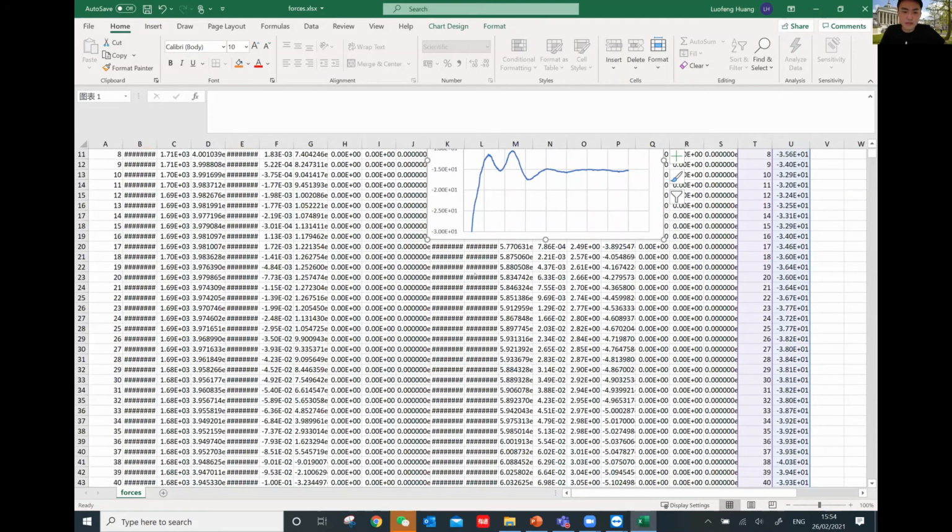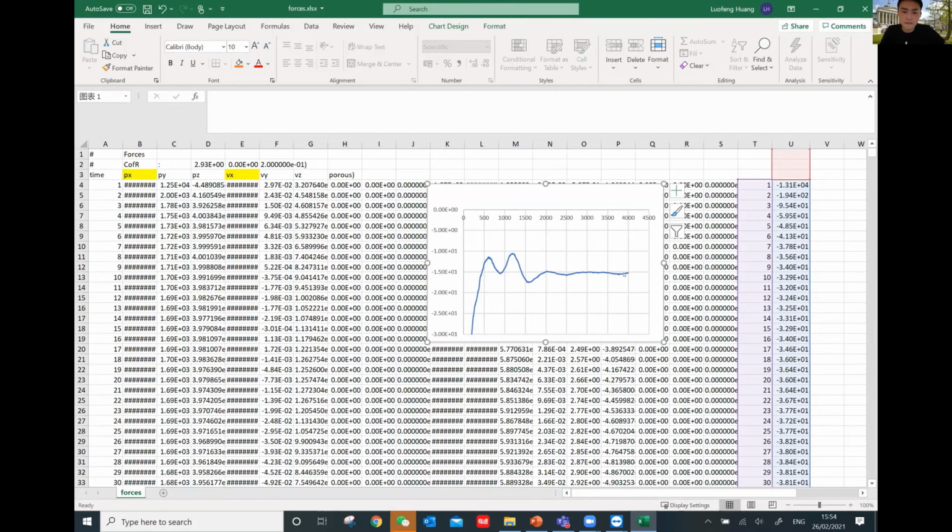it will be like this against time, and it finally comes to some value, around 15. Around 15 is the result. And one important thing here: remember the ship is symmetric, so normally we just put half the ship inside the domain, calculate the force, and times 2 in the final result. So the total ship resistance here should be 30-something, maybe 30.5.